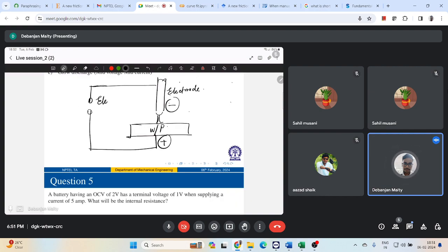This is my electric source, right? Now how does this arc generate? I will come to different classifications of this electric source in terms of DC, AC, rectifier, inverter. You have different kinds of power sources. Before that, we should understand how this electric arc is generated. There is something called thermionic emission.